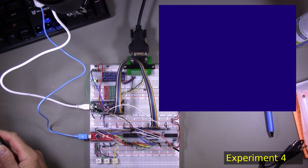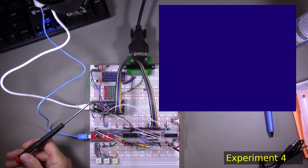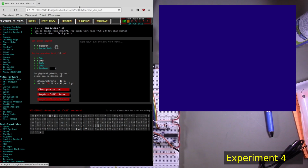Once I had a proper command protocol implemented where I could have data associated with each command, the next thing was to upload some font data into the block RAM of the FPGA. I found this nice website, int10h.org, that had a whole bunch of different IBM PC fonts. The one that I chose was DOS ISO 8. I don't know how widely used this was, if it was ever used on an actual IBM hardware device, but it's a pretty nice font.